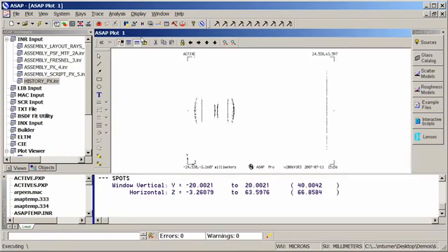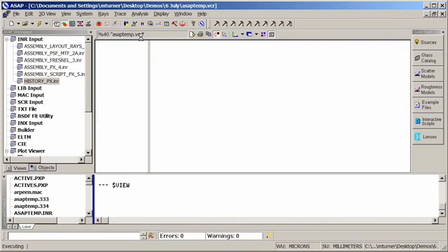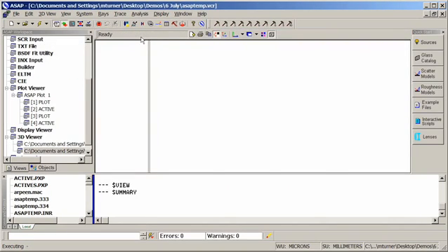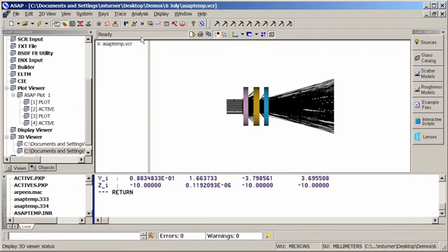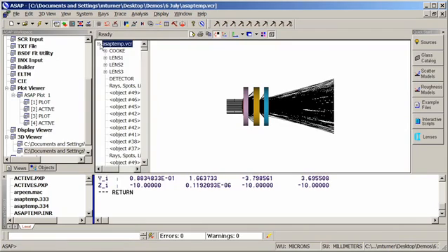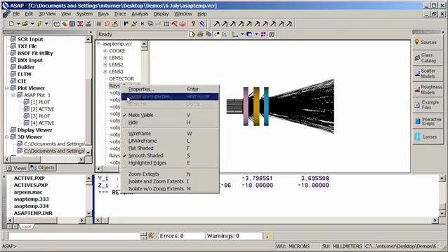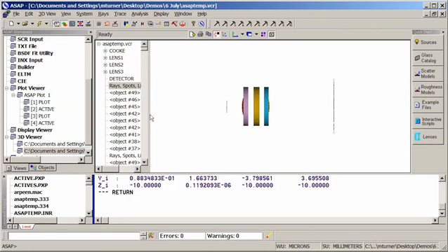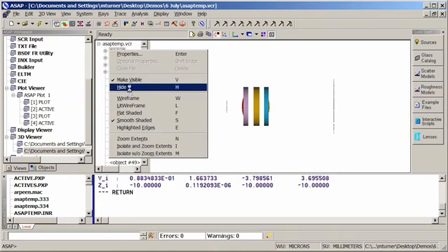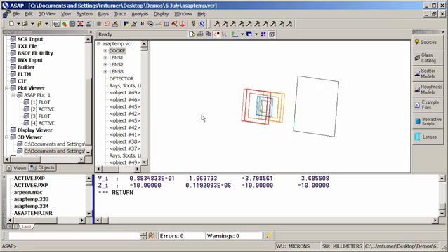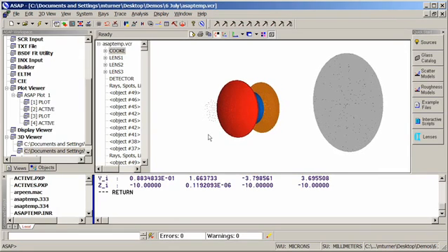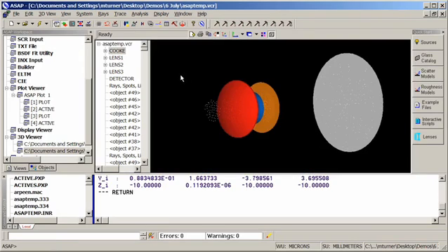And what we see here are the surfaces that rays were on just before they exited the system, as well as those rays that are on the detector. And initially this looks a little bit scary, but if I open the list of objects, let me hide all of the original ray paths. And I'm also going to hide the mechanical structure so it will allow us to see things a little bit more clearly. And now let me rotate and zoom a little bit. And what we see on these surfaces, these little dots, let me change the background color, make it a little easier. These are where some of the Fresnel reflections were then lost from the system. These were rays that didn't make it through.